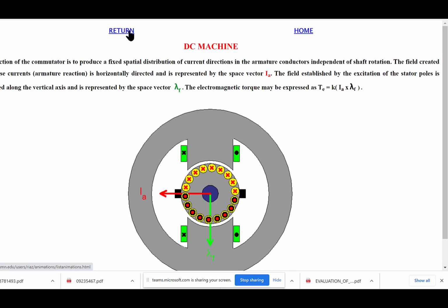But it's interesting. A brushless DC machine is actually a synchronous machine, and it uses power electronics to orient the directions of the currents so that you mimic this maximum torque per ampere relationship. It actually makes a synchronous machine look like a DC machine.